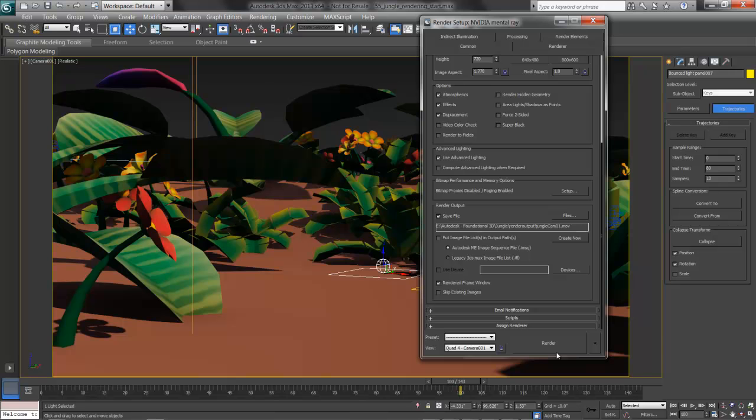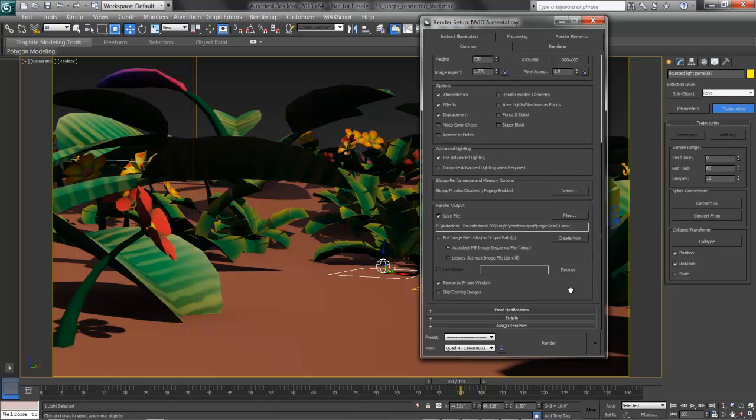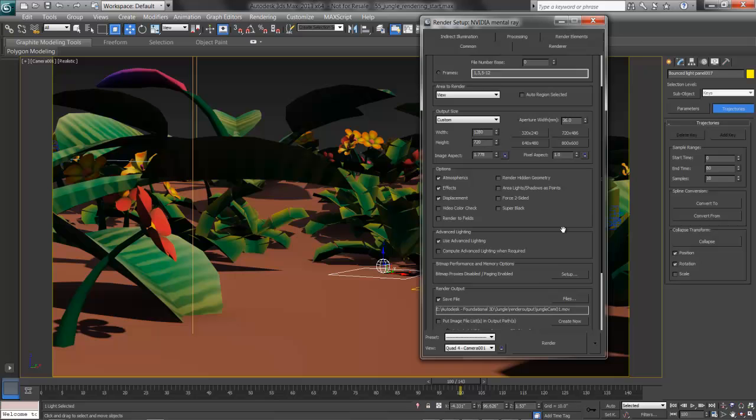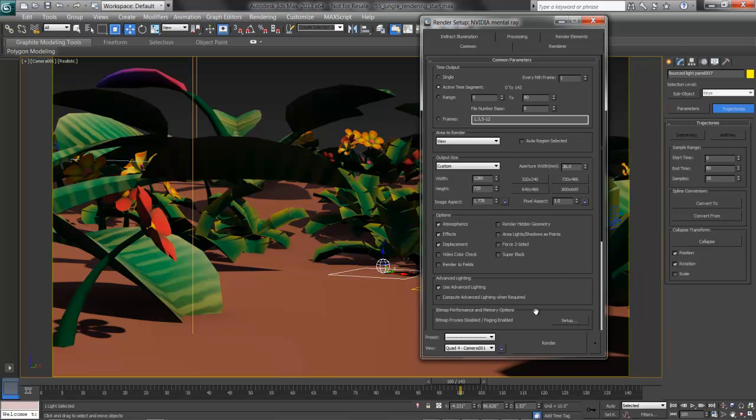It's important when you go to hit Render to make sure you've assigned all the textures, you've tested the lighting, you've tested the animation, you've previewed it, you've checked your settings, you've checked your anti-aliasing in the rendering. Looks like I'm a little low there and I should switch to 1. I also want to make sure that the file's going in the right place. All the textures are there. Nothing's showing up black. I've decided how I'm handling the background, which in this case is going to be my daylight system. All these things factor in. When I'm all ready though, I'll hit Render and pull up the files.